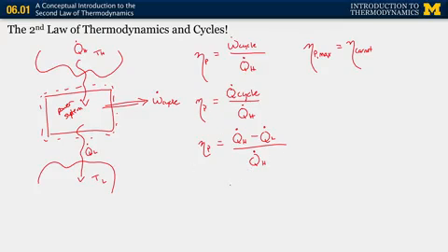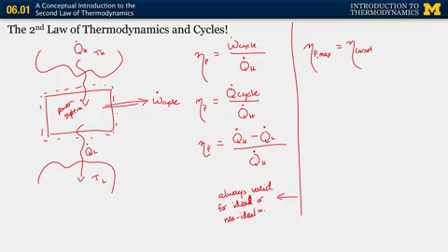But if you look at this expression, and again, everything on this side of the line is valid for any power cycle anywhere, ideal or non-ideal. These are always valid, right? This is just a definition of an efficiency, and then when we do the substitution from work transfer to heat transfer, that's just a statement of the conservation of energy, a statement of the first law. So these are always valid for ideal or non-ideal systems. And non-ideal systems is another way of saying real or actual systems.